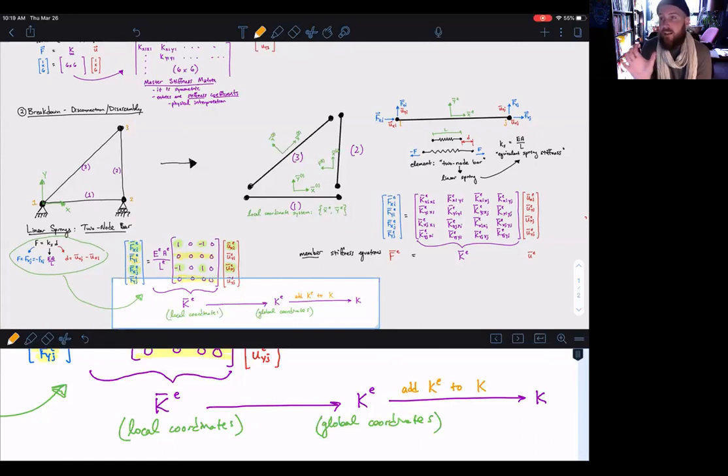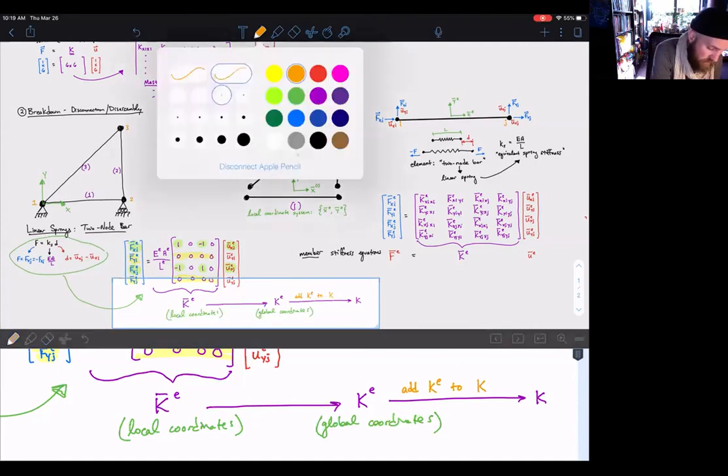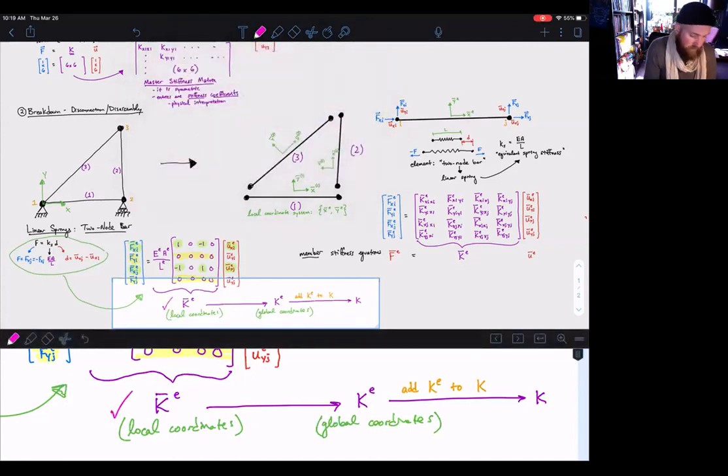which is our way of, conceptually, taking how stiff each element is and helping to construct the overall structure, so that you have some sort of global stiffness matrix defining how rigid the structure is, or how much that structure resists deformation. So at this point, we're done. And the next step is to go between the local and the global coordinates.